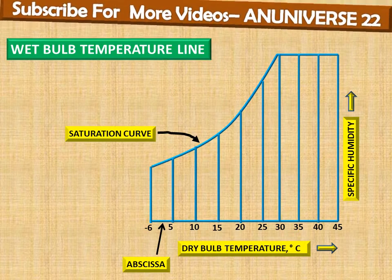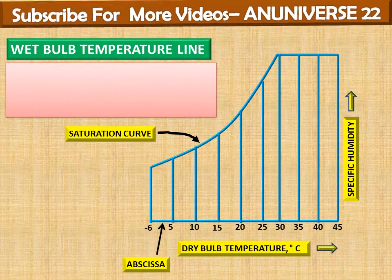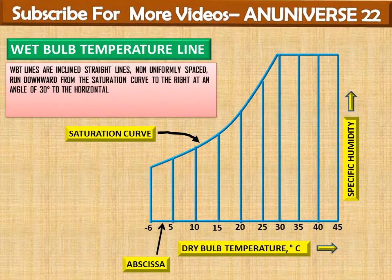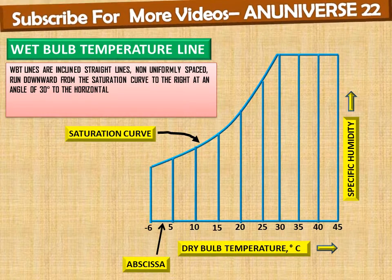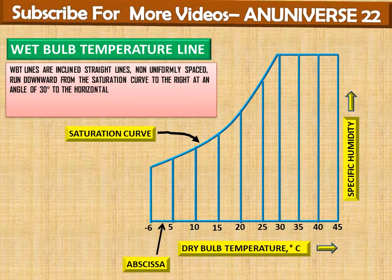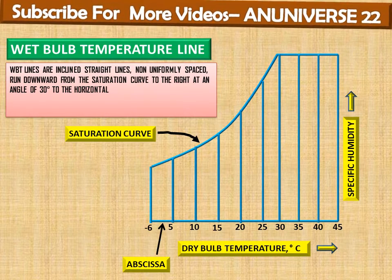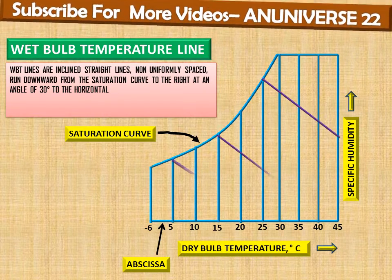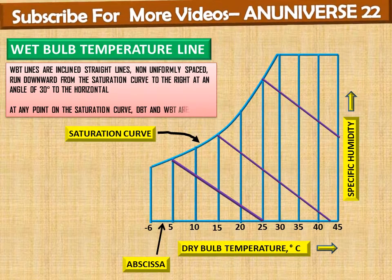And the second line is the wet bulb temperature line. The wet bulb temperature lines are inclined straight lines, non-uniformly spaced, running downward from the saturation curve to the right at an angle of 30 degrees to the horizontal. So these are the wet bulb temperature lines.